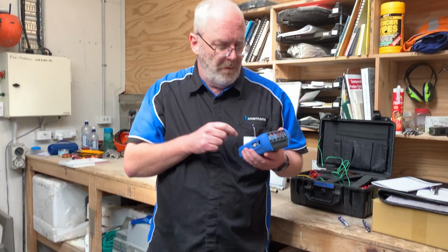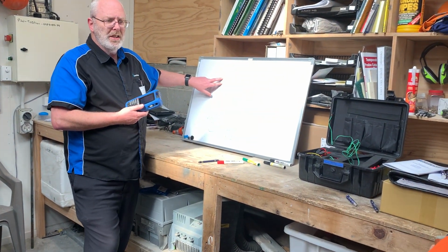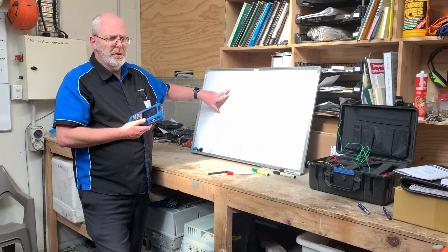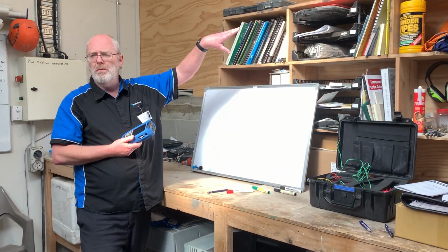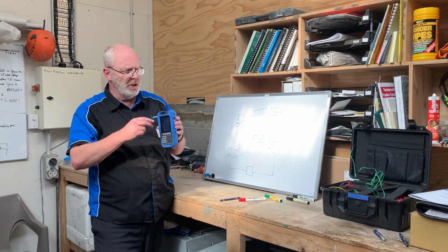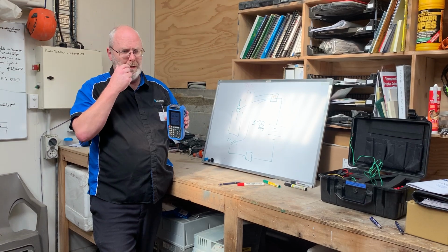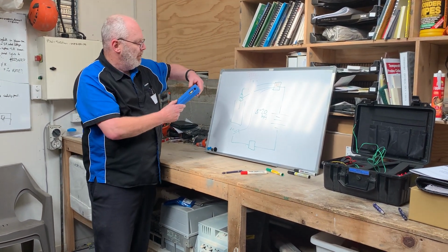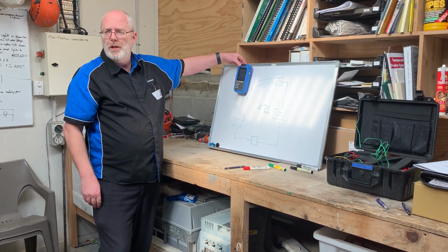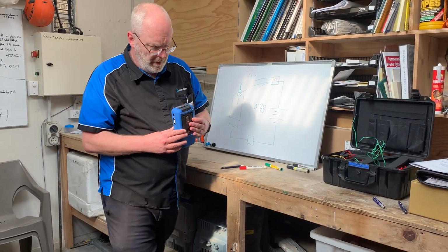You can even, and I've not seen this done very often at all, simulate the transmitter. Let's say you thought that the transmitter in the head or the transmitter on the rack was dodgy. You can actually put the thermocouple or the RTD into here and have it act as the transmitter and give you the 4 to 20. So have this replacing the head mounted one. It really does absolutely everything in the loop. Now, a couple of extras.